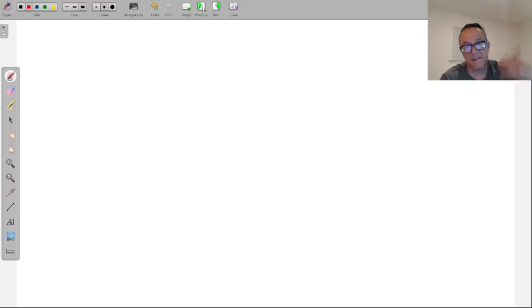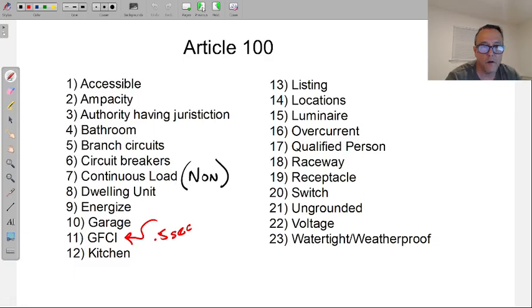So now you have kind of an understanding of where these wires get ran. Low voltage stuff can be in those areas without conduits, without like being in a piece of EMT or any kind of flexible conduit, because that ceiling area is considered a raceway in and of itself. So a lot of different types of raceways, but the most common ones are going to be the conduit type.